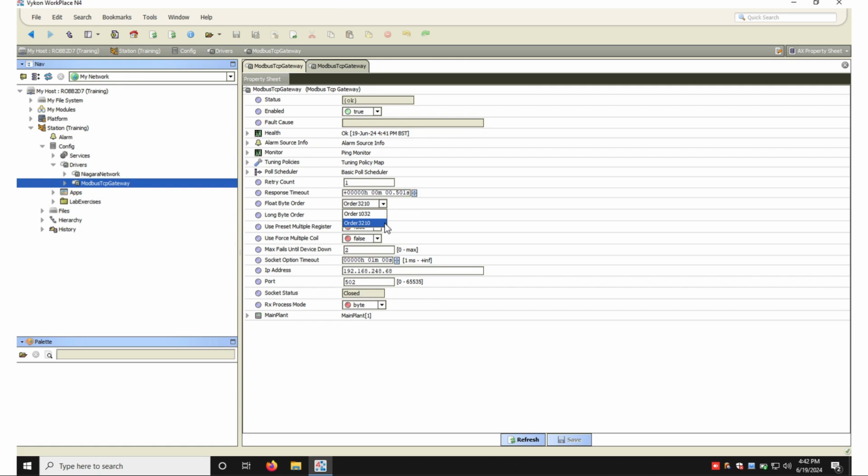Or do we need to swap those bytes around to reorganize the number that's received? It will be more often than not a bit of trial and error, reading the documentation and understanding what you're going to get back, and then maybe playing around with the settings to get the right values because every manufacturer likes to do it in a different way.